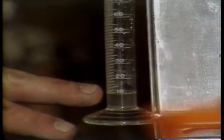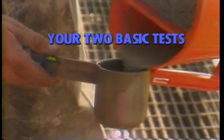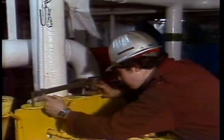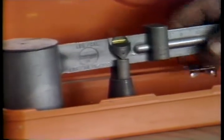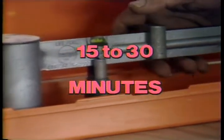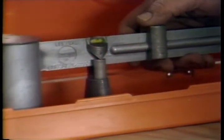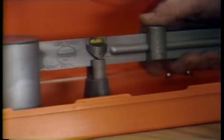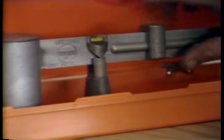Changes in the mud characteristics are what we're looking for, and to find them, a whole array of tests are performed. It starts with your two basic tests, mud weight and viscosity. We'll start with mud weight. When we talk about mud weight, we're really referring to mud density. Mud weight is usually taken every 15 to 30 minutes to help the driller and mud engineer determine whether or not the weight is remaining consistent. The intervals of checking might change according to the activities on the drill floor.